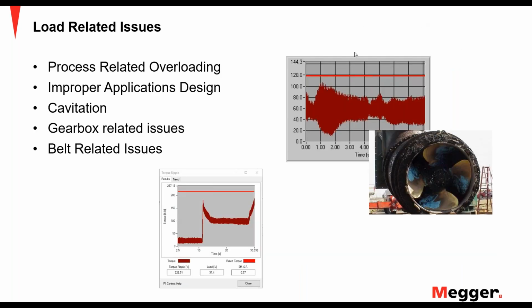We see another use here in the torque. This is a picture of a cavitating pump. The end bell had fallen off the end of this pump, and so it wasn't directing the water flow. And so that's cavitation. It's a classic look of cavitation. We can tell here in the torque ripple whether load has changed in the middle of our acquisition. In that 30 seconds, the load changed here and back up, it changed again here. So there are things that we can tell about what's going on in the process when this happens.